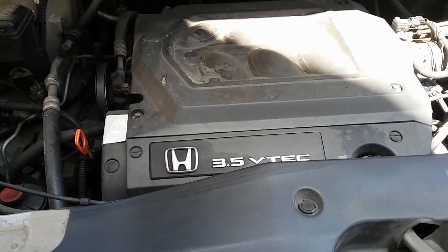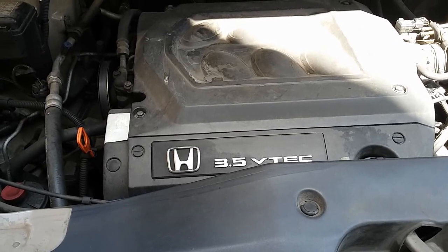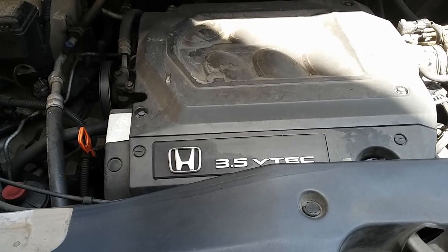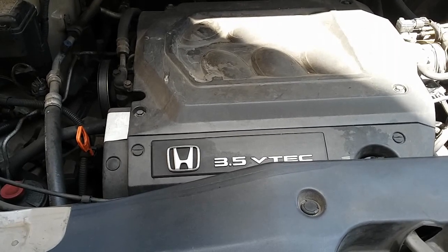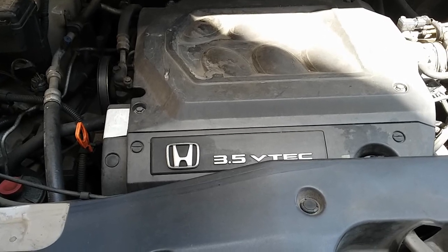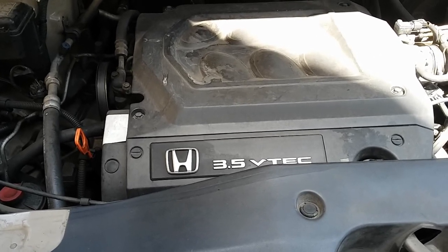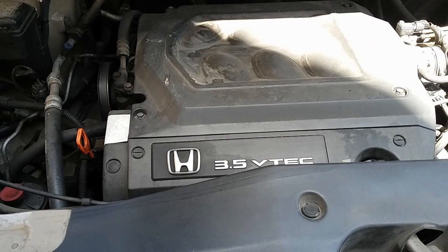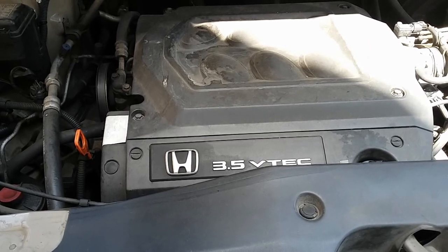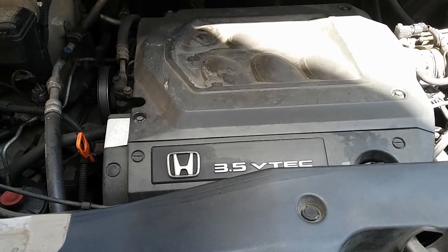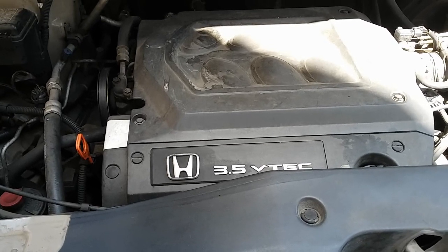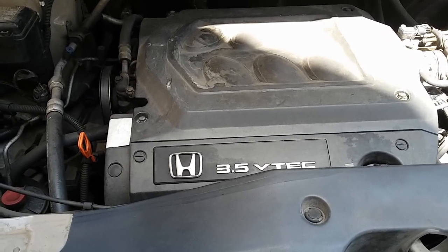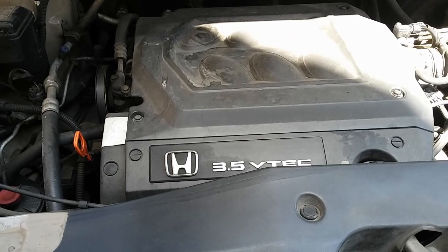You know, let's not forget this is an 18 year old original cat. So there's probably a moment where the computer sees that the cat is not producing its potential. I'll say this is normal for an aging cat, but the Muffler Shop diagnosed this vehicle's cat as a replacement. I'll say that this cat is still working properly, but it's up to the customer if he wants to replace it or not. But this diagnosis still proves that the catalytic converter is still working to its efficiency.